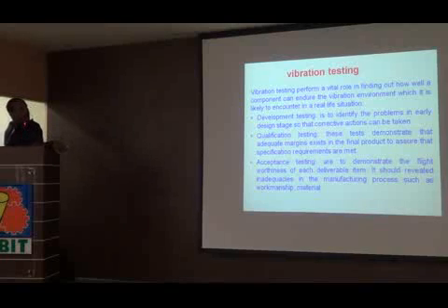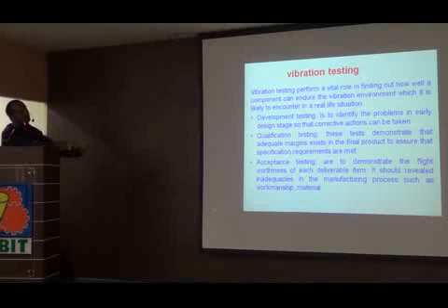Acceptance test is like a production test. Once you are done with all your testing and have frozen your design, you have produced items in bulk quantities. Now you have to know whether all these produced quantities are meeting your specifications. So at that time we do one-to-one testing. Every item in the production line will be tested, but not at the levels used in the design stage, rather at lesser levels, just to check that everything is okay: the process, the manufacturing techniques, the workmanship. So these are the differences.